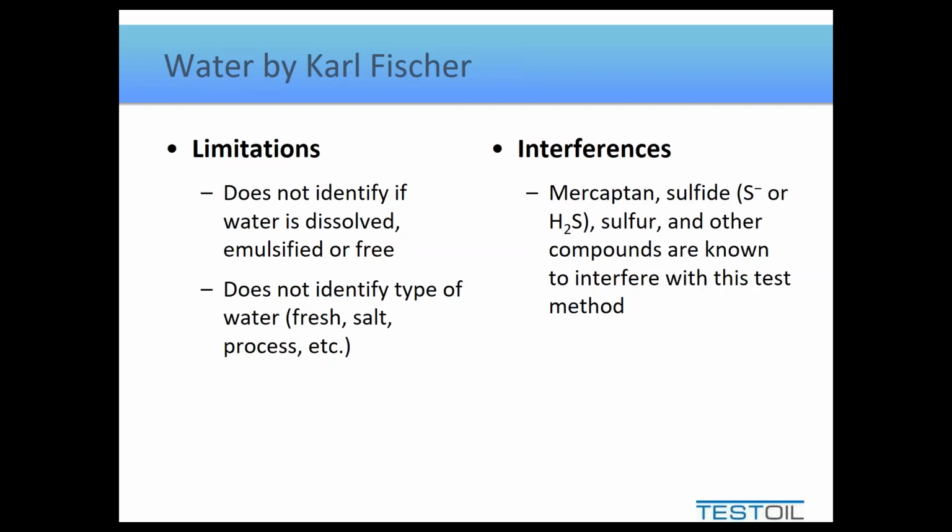Now, the limitation to a Karl Fischer test is it doesn't identify what phase the water is in. So it doesn't know if it's dissolved, emulsified, or free. It also doesn't know where the water is sourced from. It can't tell the difference between, as an example, fresh water, seawater, or even process-related water. So we don't get any solid information there. We just know how much water of any type is present.